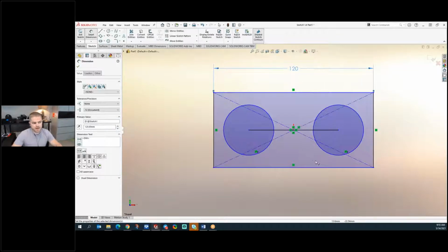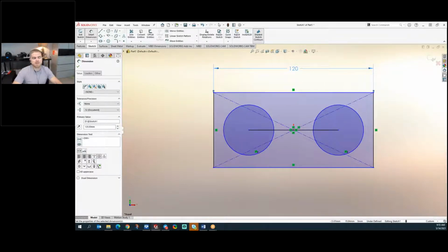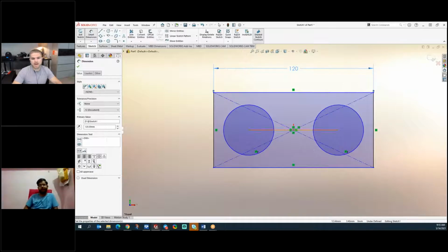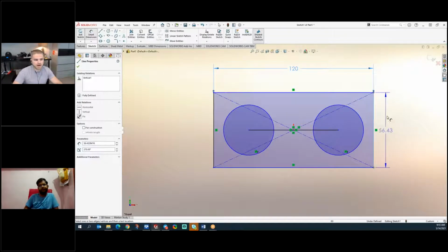It actually, in that single moment, scaled down all of my sketch entities with that first dimension. That's why it's powerful in SolidWorks that you don't have to really worry about your dimensions or your sizes while you're sketching that first sketch. Just get it close, just get it proportionally correct for something that works for you. And now when I go to lock everything else down, they're all pretty close. They're all not too far off of what I know I want them to be.